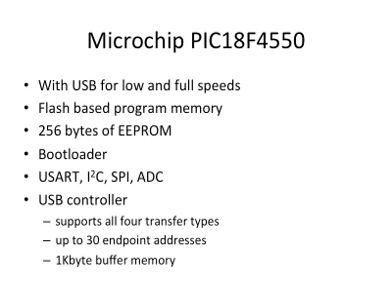This bootloader stays there all the time. With this piece of code, you can update the application segment without using a programmer tool. So that's the main purpose of the bootloader, which is very helpful if you want to upload or update the firmware after the chip is deployed.